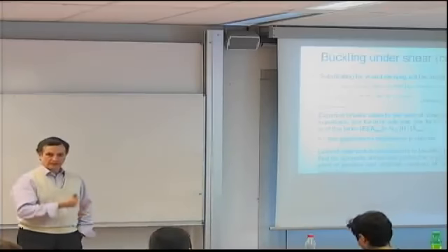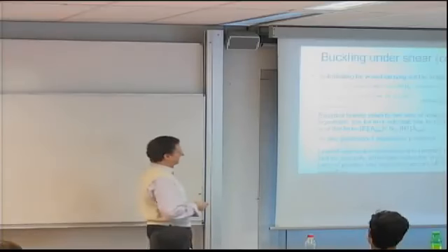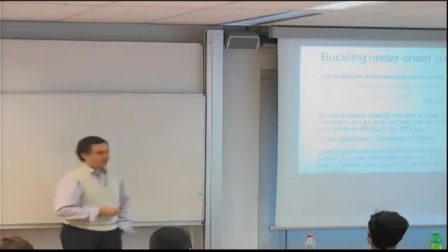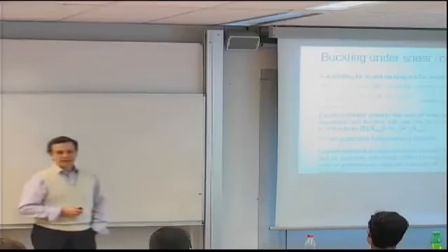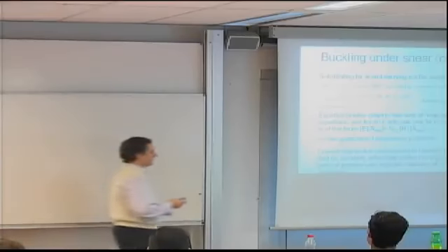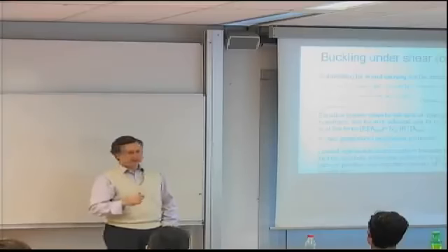And that's where you now have to solve it, and it's quite challenging for some types of problems to have a good subroutine. I mean, MATLAB does eigenvalues and all kinds of other software. You solve it and you have to find the lowest eigenvalue, and that becomes your buckling load. Now, lowest in absolute value, because you can have positive and negative values.